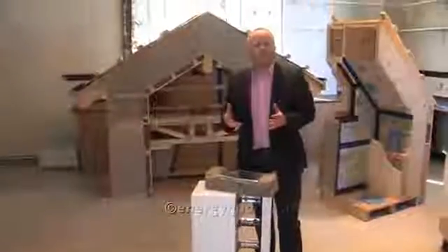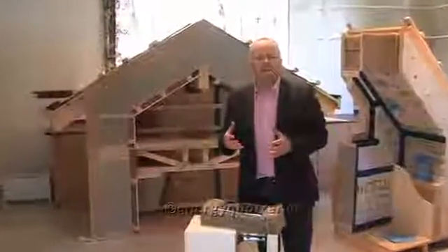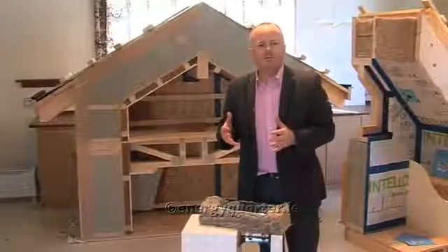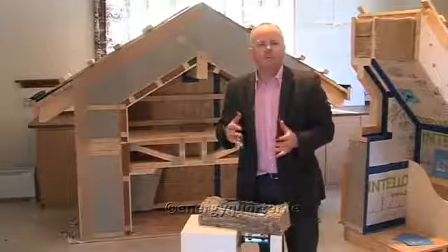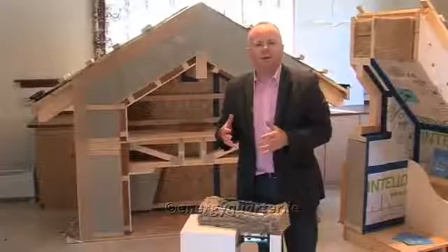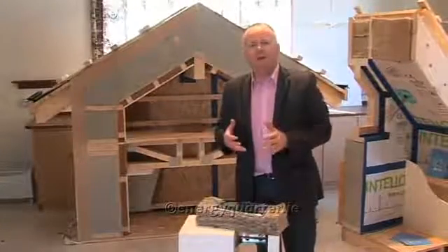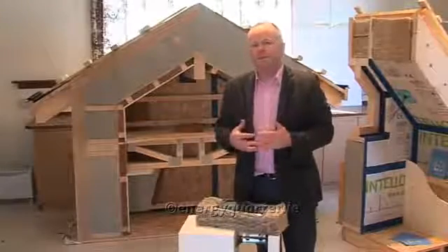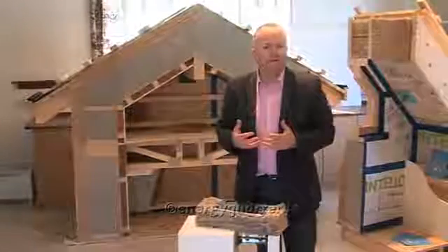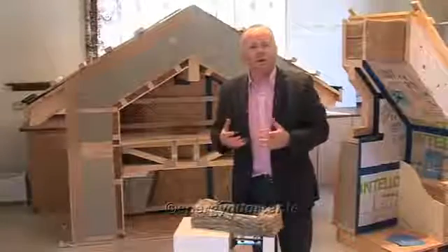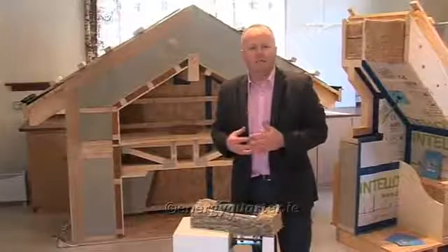So we know the Passive House standard requires an incredible amount of insulation, and we have certain target U values. So for example, somewhere between 0.10 and 0.15 is what we need in the walls, in the roof and in the floor. But the Passive House Institute don't give us any direction, for example, on what materials we should use. So we're free to use whatever materials we like to insulate our house.